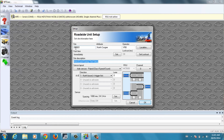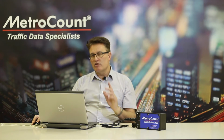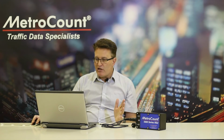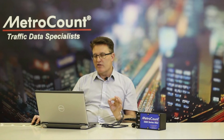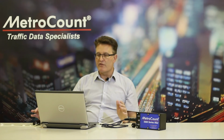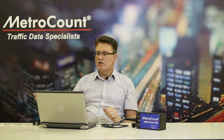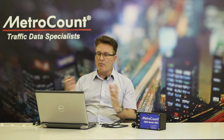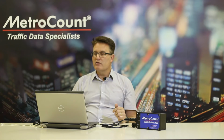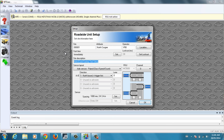Here's the site description. Now, notice how we had a site number or a site identifier. Some people put a lengthy description in the site identifier. That's fine, but the site identifier is usually used by some other computer program, computer system afterwards. Say if you're doing surveys for a state road authority, they may have a special numbering system where the number is the key for uploading the data afterwards. But it's the site description where we can put a human readable description for the survey location. So we're at Socrates Parade, south of Draper Street.